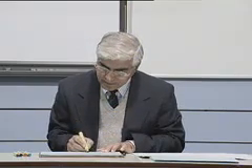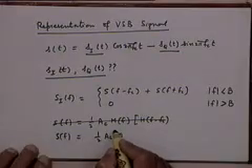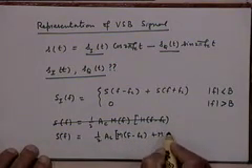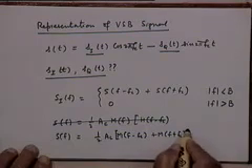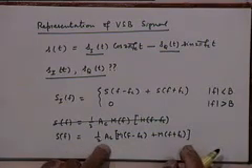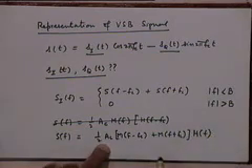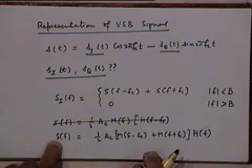How was it being generated? You are generating it by first multiplying m(t) with cos omega c t and then passing through the VSB filter, right? So that spectrum would be M(f minus fc) plus M(f plus fc), right? This is the DSB-SC signal in the frequency domain, and you are passing it through H(f). So this was S(f).